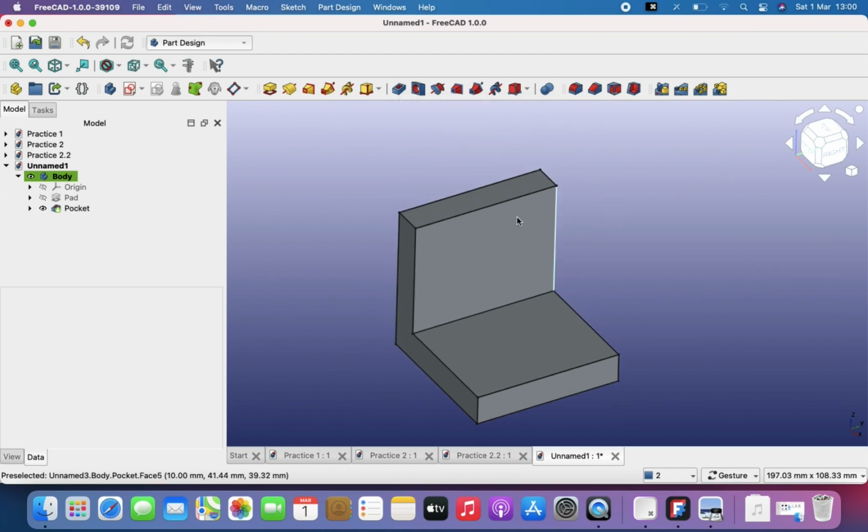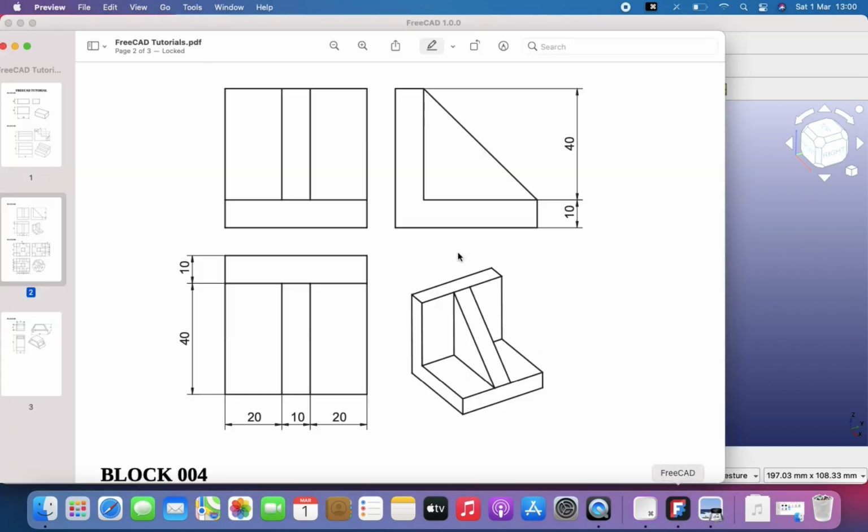And then the next thing I want to do is that face, this triangular face that comes down here. There are quite a few ways that we can do that, but I'm going to try a method, and I want you to follow me closely. I'm going to go to the plane here, not the plane on top, the plane under here, and create this profile, like it shows here, a 10 millimeters by 40 millimeters profile. Then I'm going to extrude it up, and then cut it again. So let me show you what I'm saying.